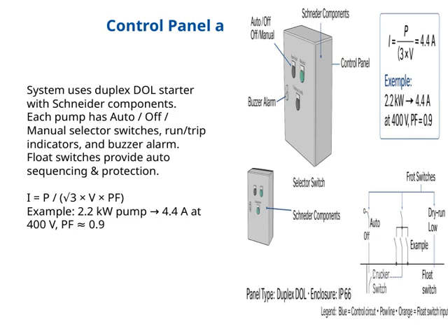The system utilizes a duplex DOL starter, which stands for Direct Online Starter, equipped with Schneider components. This setup ensures reliable and straightforward control of the pumps. Each pump has its own control switches, specifically auto, off, and manual. These allow operators to select the desired operating mode easily.